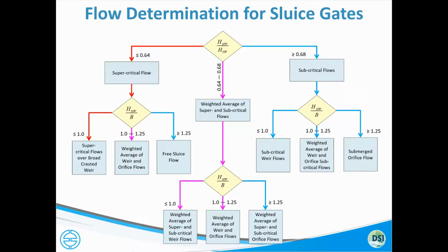So you've got everything from supercritical flow and subcritical flows and submerged flows, and EFDC is handling these flow conditions and deciding appropriately how to conduct the actual hydraulic calculations.